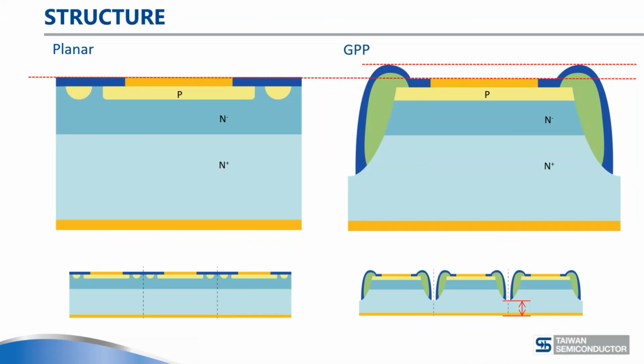The GPP process is an older process. I think only triacs are still made using GPP, and rectifiers, and I think also some thyristors, maybe the smaller ones. Other processes for discretes tend to be all planar, which is a standard diffusion technique. With this GPP one, we etch a moat. A moat is something you have around a castle, and that's the best way of looking at this GPP slide.